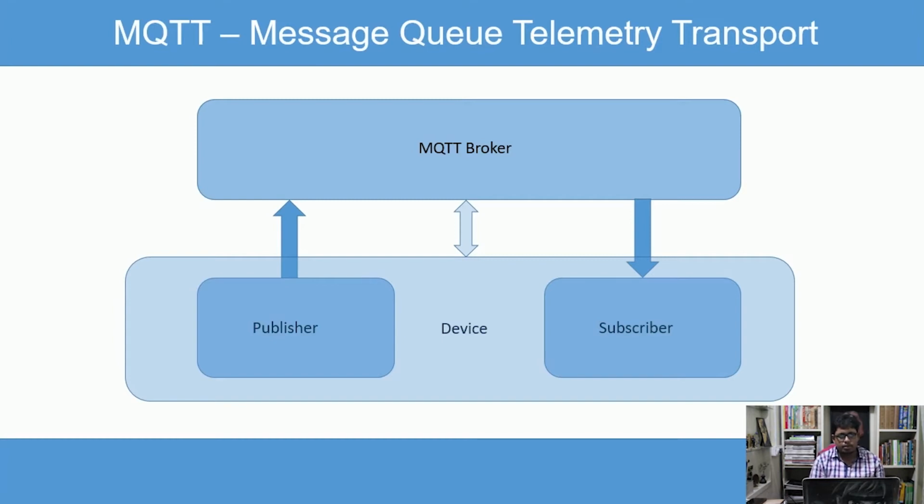If my MCU is a subscriber, then whenever I publish a message from the mobile app to that topic, the MCU receives that message. Similarly, on the other side, when I'm sending a message from the MCU using the MQTT protocol, the mobile app is already subscribed to that topic, let's say video, and whenever I publish some message from the MCU, the data is received on the mobile.